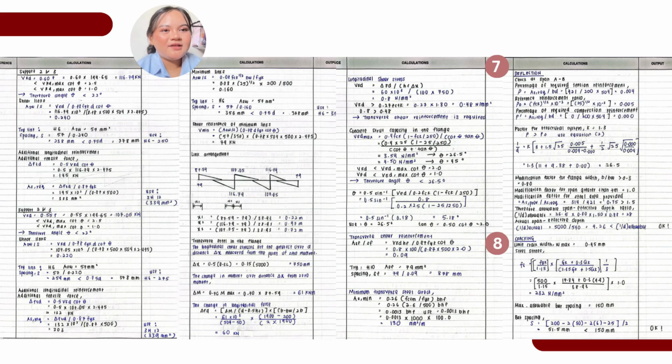Pointing to the link arrangement diagram, we also map out the link arrangement, identifying the zones where we can reduce the shear reinforcement to nominal links once the shear force drops below a certain threshold. Finally, we must ensure the beam performs well under everyday use, which means checking the serviceability limit state, specifically deflection and cracking.